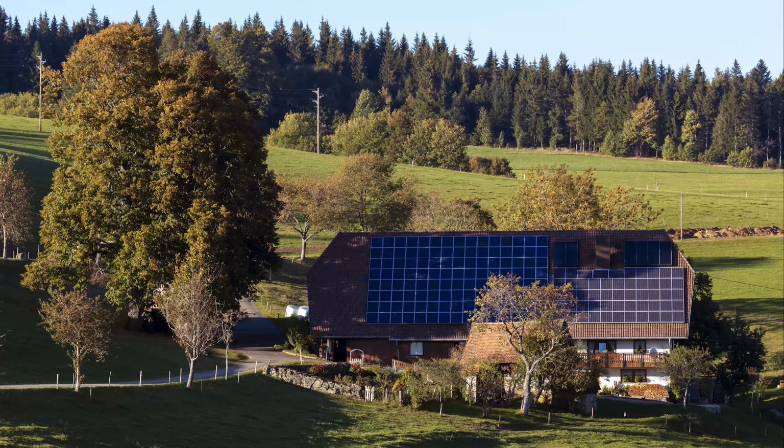Now what I've showed you so far assumes that your solar array isn't going to be shaded by trees, buildings, or indeed the horizon itself, if there's higher ground to the south of your building. This is really important because PV systems can lose a lot of their energy yield if they are frequently shaded. The extent of any shading varies over each day and over the course of the year, so we tend to use software tools to quantify and analyse what impacts the shading could have on the energy yield.